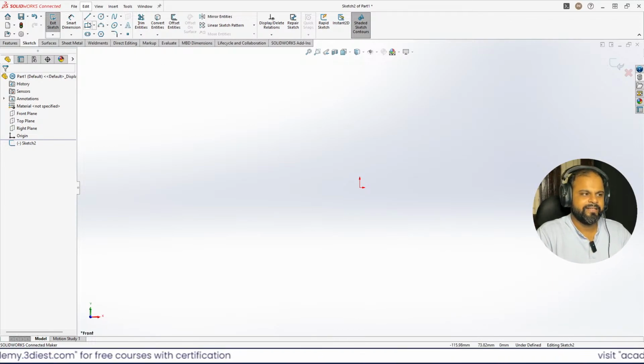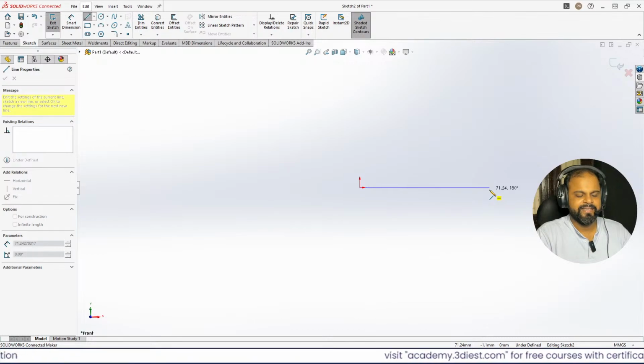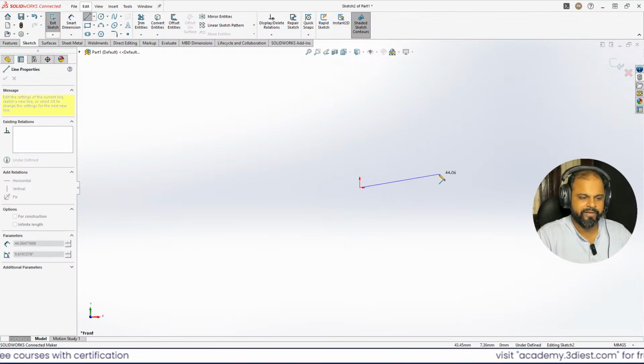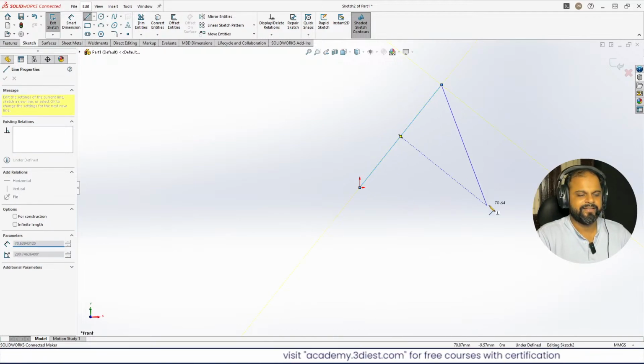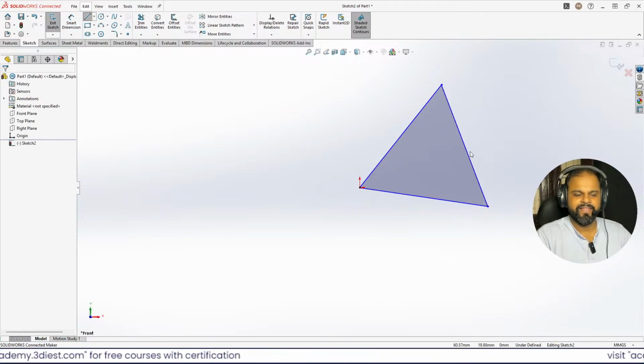So whatever numbers you see, let me start this line tool, these numbers are all in millimeters, like 71 millimeters, or if I decrease it, it's like 29 millimeters. If I go to a particular angle, it is like 27.86 millimeters. All these numbers are in millimeters. If I want to create something out of this line, let's say a triangle, I can just click, click, and click. Each time you make a single left click. Then the last point I connected to the start point of my line. This is how we got a closed shape.